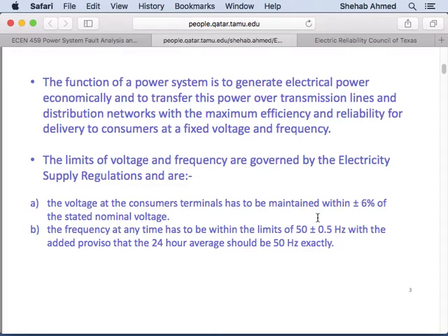And that's why, for example, here versus the US, the US operates at 60 hertz. Saudi Arabia has parts at 60 hertz, parts at 50 hertz. Airplanes operate at 400 hertz. If you go work for Qatar Airways, for example, the electrical power system in an airplane is a 400 hertz system. Why? 400 hertz is better for size. They wanted to reduce size and weight. It's important to reduce size and weight in an airplane, right? At the same time, you still want useful devices that can operate in certain speed ranges without adding additional electronics, right? So it's an optimization.